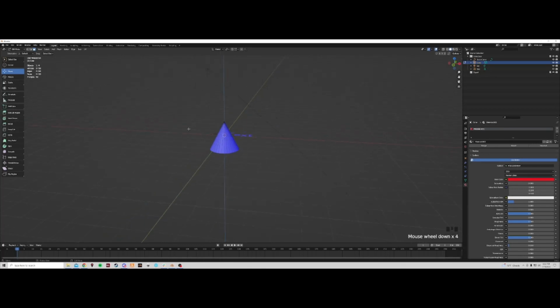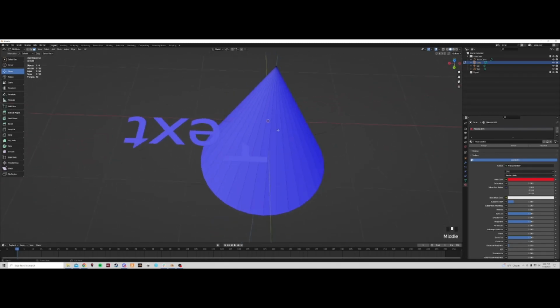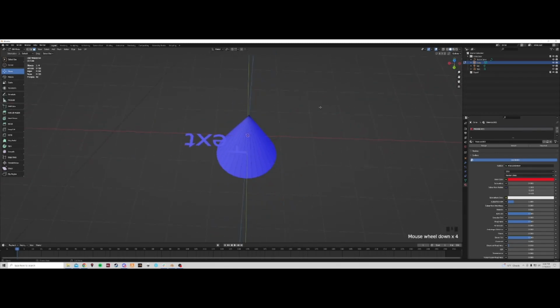Now, there are other tools that are very handy. A selects all. If you're in edit mode, it will only select all of the faces or vertices or edges, whatever you have selected up here, vertice, edge, face, it will select all of them. Now, I believe it's Shift A. Nope. Control A. I don't know. Alt A. Yeah, Alt A. There we go. Alt A deselects all. Which also would be the same as just clicking right here. Click here, deselects everything. So however you want it.